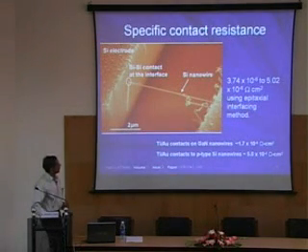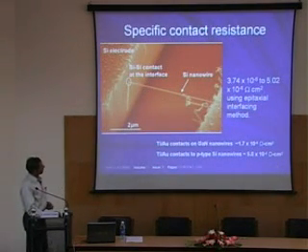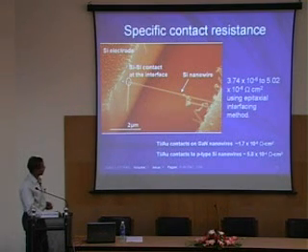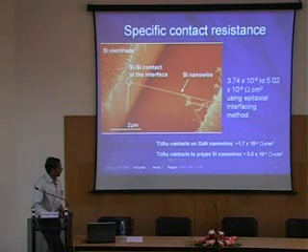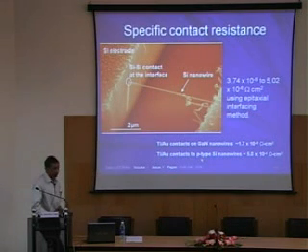When I use these nanowires as interconnects, it is also absolutely important to know the specific contact resistance when this nano bridge is touching my silicon electrode here. Typically in current CMOS technology, if I use titanium-gold contacts on p-type substrates using silicon nanowires, this is the kind of contact resistance we get.